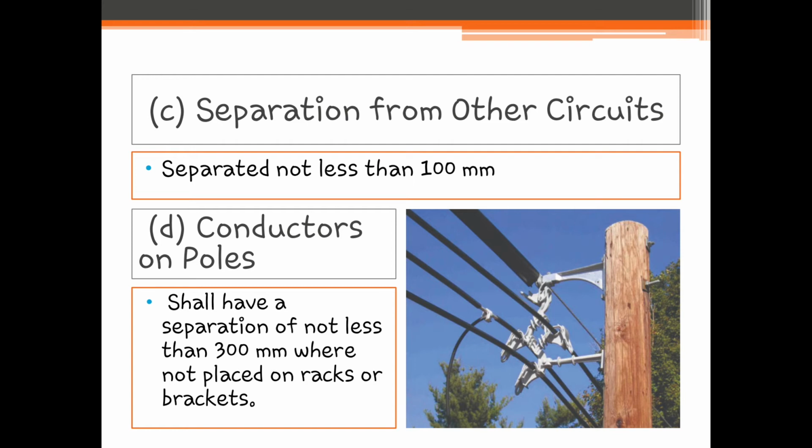So number 2, power conductors alone or above communication conductors. So we have 300 volts or less, we have 600 millimeter, 750 millimeter for over 300 volts. Communication conductors below power conductors, same as power conductors. Number 4, lastly, communication conductors alone. Wala siya requirement.